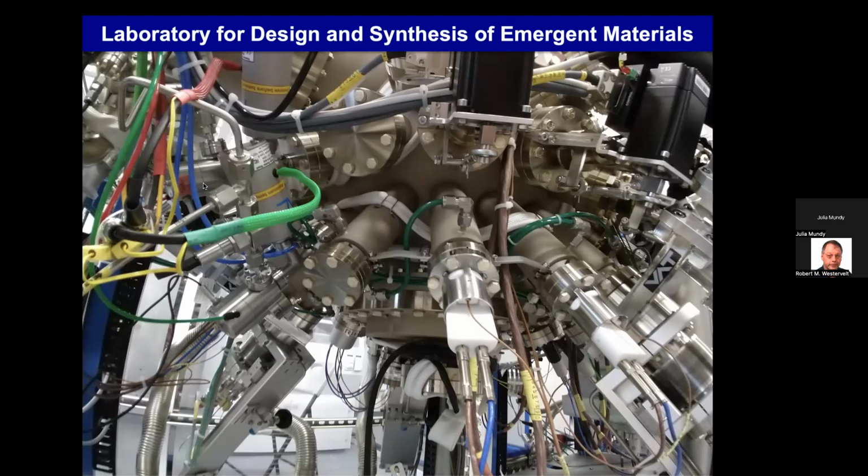How mature of a technology is MBE? Is it basically the same level of reliability for a while, or is it something that's being advanced? I think there are some advances. This is kind of a new cell with the bellows and the differential pumping. Some people want to heat the substrate super hot, so they're firing CO2 lasers at the material and doing laser heating, as opposed to resistive heating, like the toaster idea. That's a really cool idea.